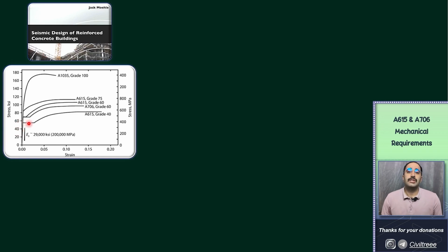This difference is generally due to probable issues with the rebar production procedure. Producers usually aim for an actual yield strength higher than the minimum value so that, given variations in properties, there is only a small chance of the actual yield strength falling below the minimum value.